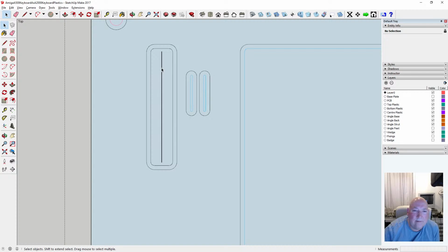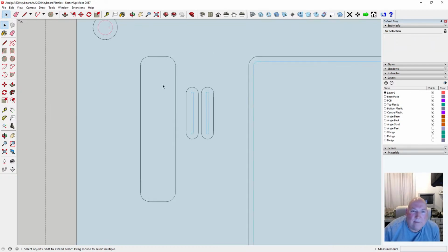Alright. So let's go. Actually, why has that got two lines? Oh, I've got it, because that's the G code it put in. Right. So we've got that there. So why didn't it like that? Don't quite get why it didn't like that. Let's try and do it a different way. So we put the pocket in. We know it's 16.67%. Now we can do a different way of doing it. If you hover over there, it says shift only zigzag.